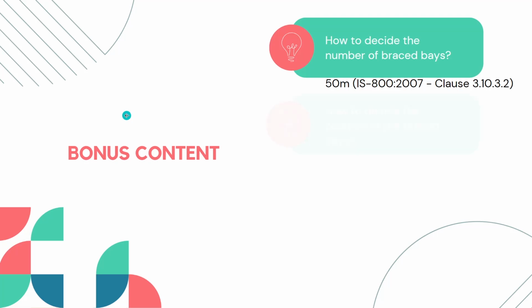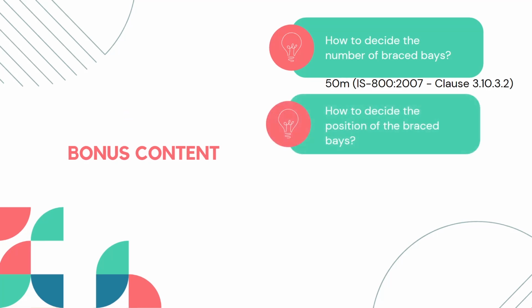Now, the second question: how to decide the position of the braced bays? As we have gone through the behavior, the wind load which reaches the top of the rafter travels through the strut tube along that line, right? So, we need to place the bracings as near to our end frames as possible, such that a portion of the wind load which comes is immediately resolved to the ground. And from there on, through the required number of bracings, we can evenly space them apart without exceeding the maximum spacing, that is 50 meter.